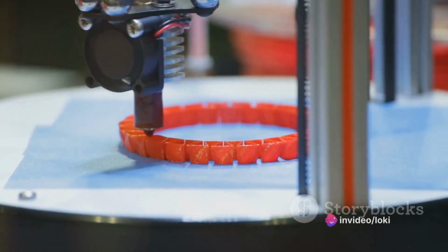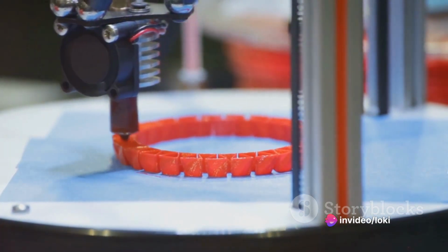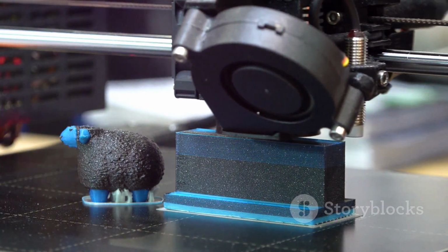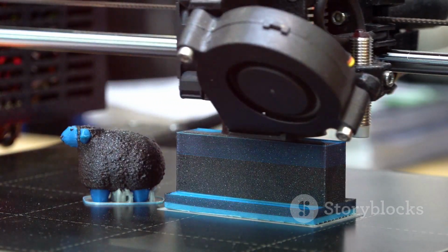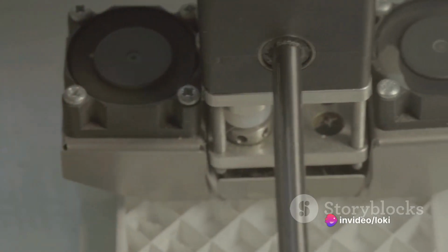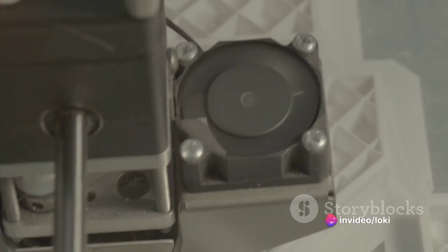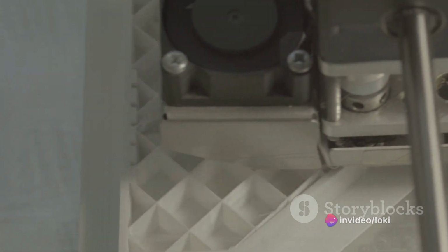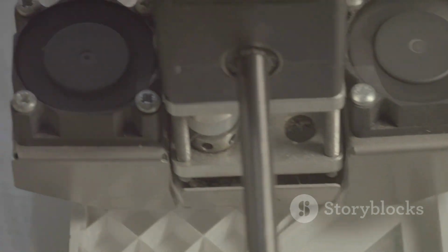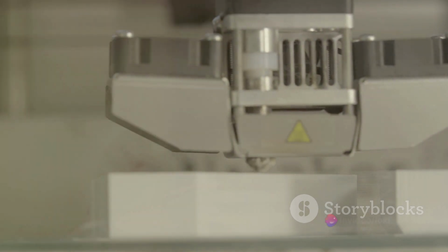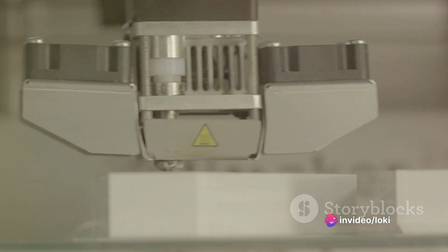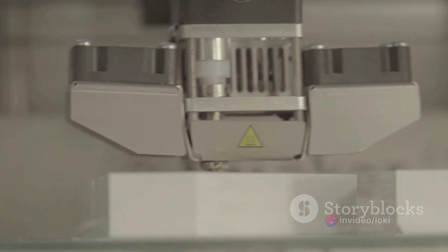The slicer not only splits the model into layers, it also calculates the optimal path for the printer's nozzle to follow for each layer. It's like a choreographer, directing the dance of the printer's components with precision and efficiency. But the slicer's job doesn't stop there. It also determines the specifics of how each layer will be printed. It decides the speed at which the nozzle should move, the temperature of the printing material, and even the order in which parts of a layer are printed. It's like a maestro conducting a symphony of parameters to create the perfect print.